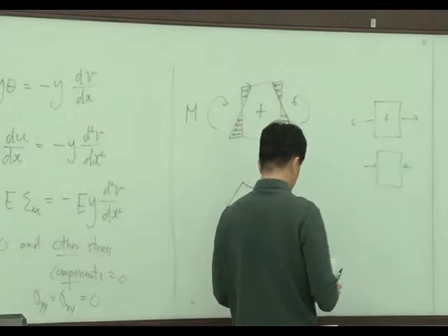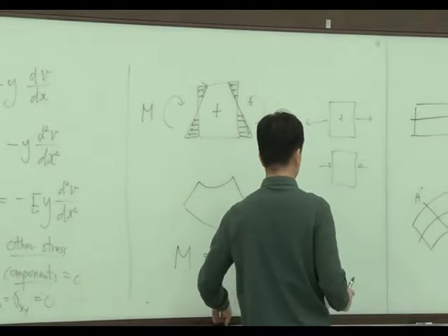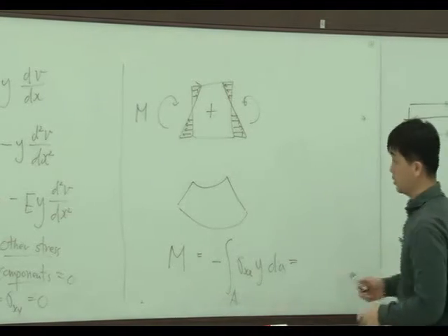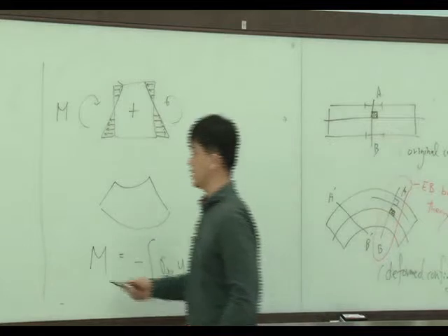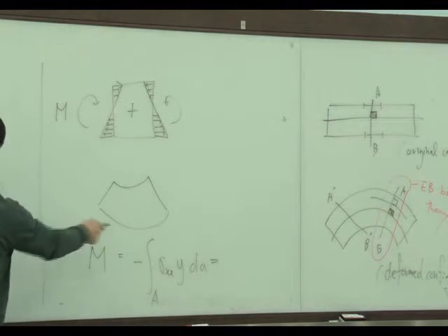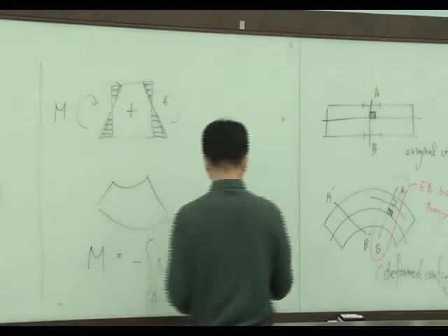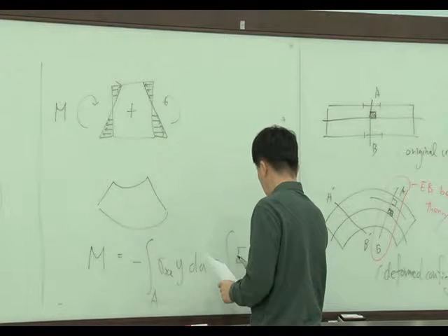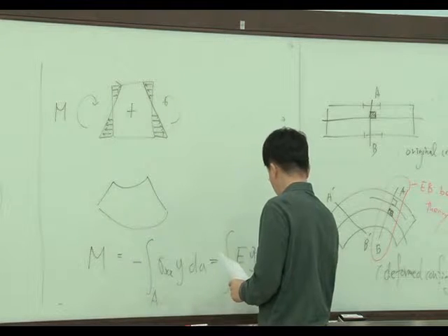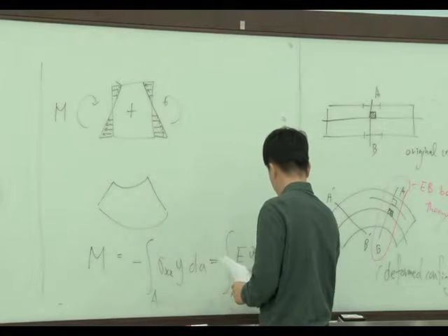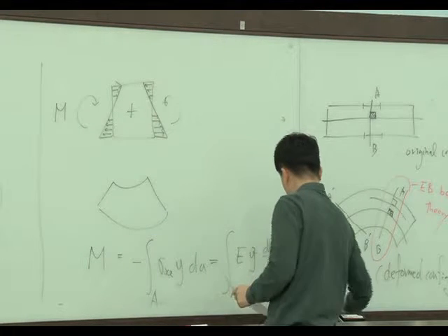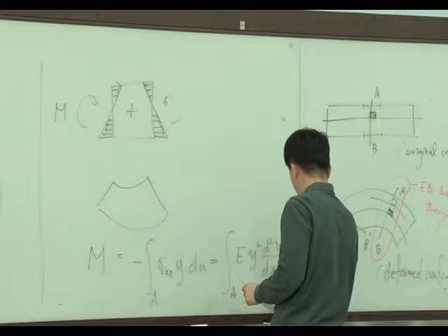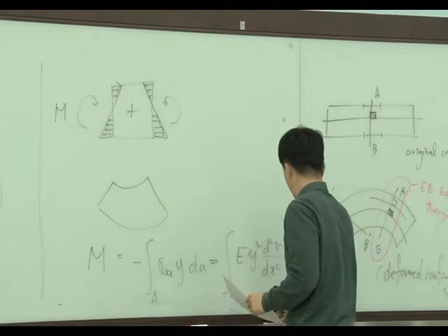Okay, so then the moment is calculated by applying this equation into here: the integral of E y squared dA times d2v/dx2.